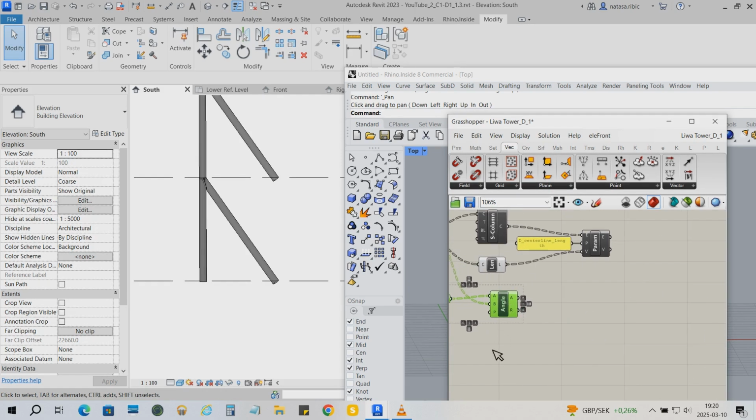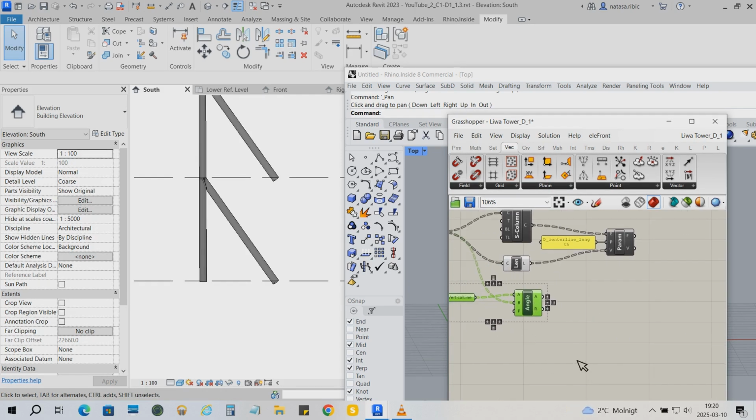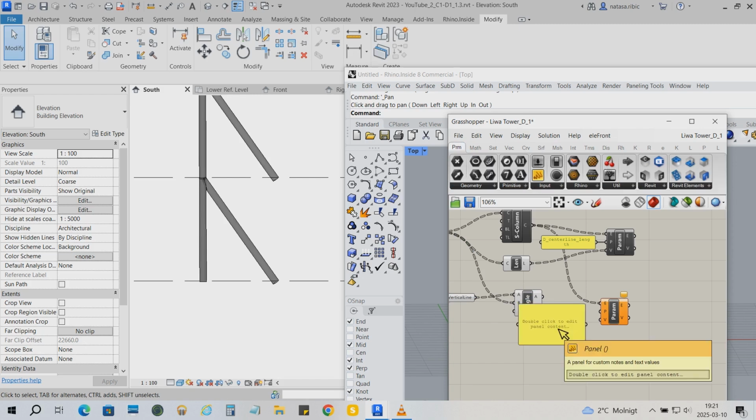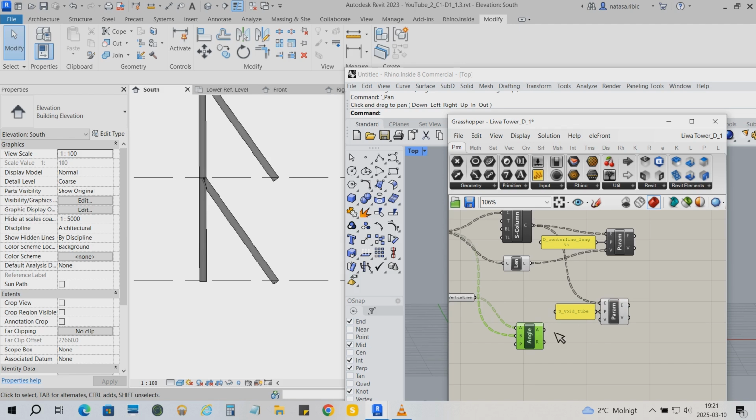These are my values. I'm going to push to the Revit project file through the Revit family and go to Revit and bring a new element parameter component. Connect the column to this E element input value. The name of the parameter is the void tube, I think. And these are my values. Let's see. Yeah, that's correct.